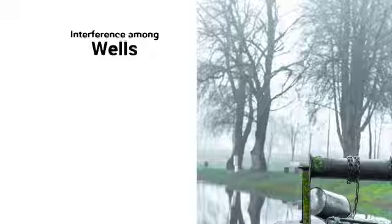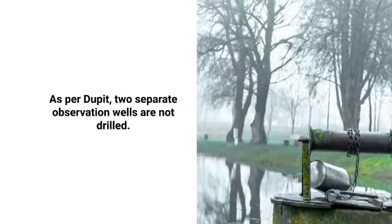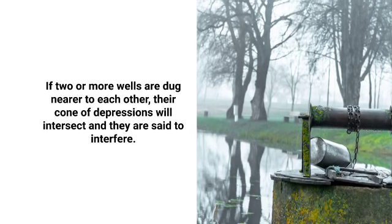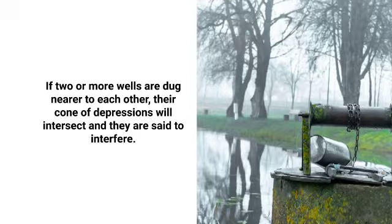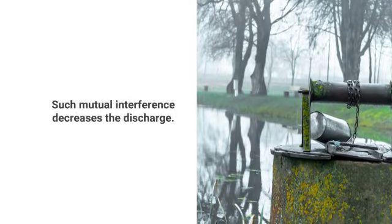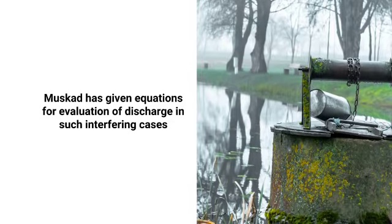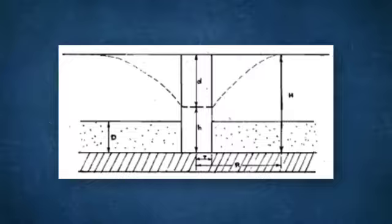Now, interference among wells. As per Dupuit, two separate observation wells are not drilled. If two or more wells are dug near to each other, their cones of depression will intersect and they are said to interfere. Such mutual interference decreases the discharge. Muskat has given an equation for evaluation of discharge in such interfering cases. So here is the picture to get that formula.